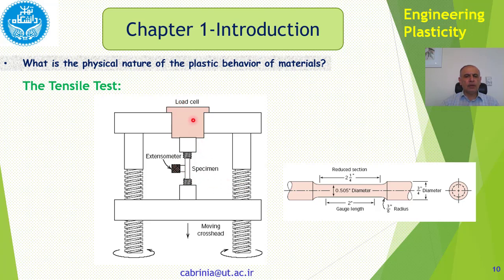Also, we have a load cell here which measures the load. As we move down, the load increases, and the load cell measures the load. So what we measure in the tensile test is load and extension, increase in length and increase in load. These are what we really measure.